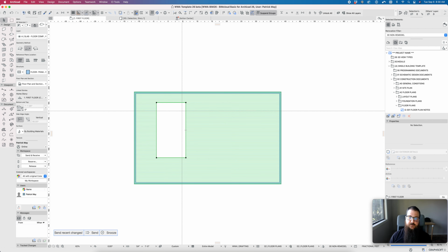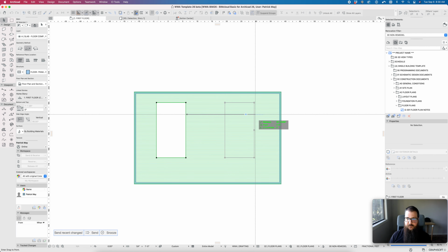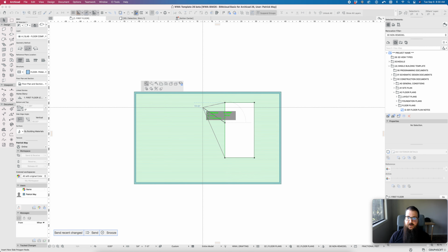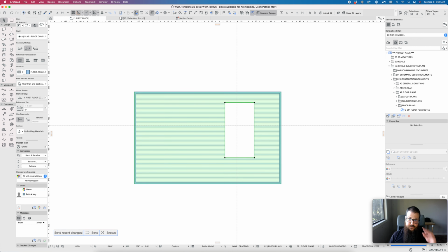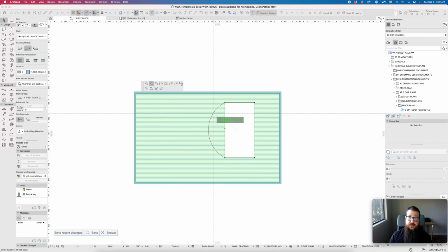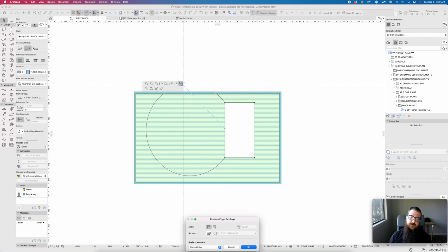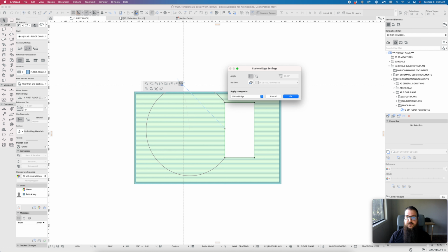That stair opening or that puncture within the slab can be selected as a separate geometry and moved, dragged around, offset edges and select nodes, create curves. The pet palette's pretty useful and versatile for the slabs. You can also select an individual segment of the slab and redefine the edge settings for that. That could be edge angles if you're using the slab for like a turned down slab edge or footing, or some kind of ramped edge.